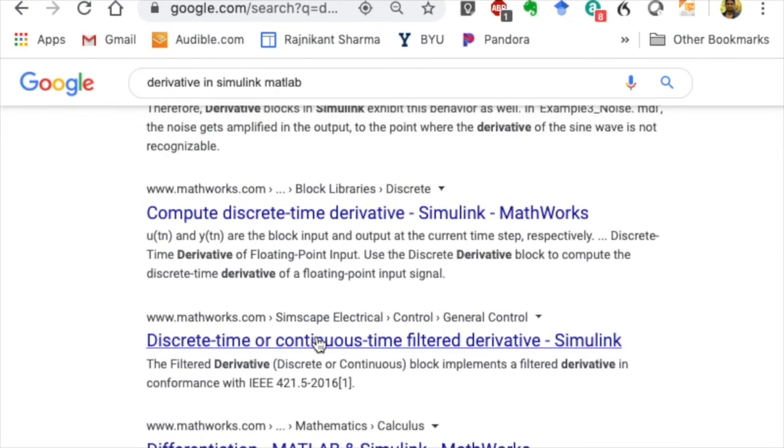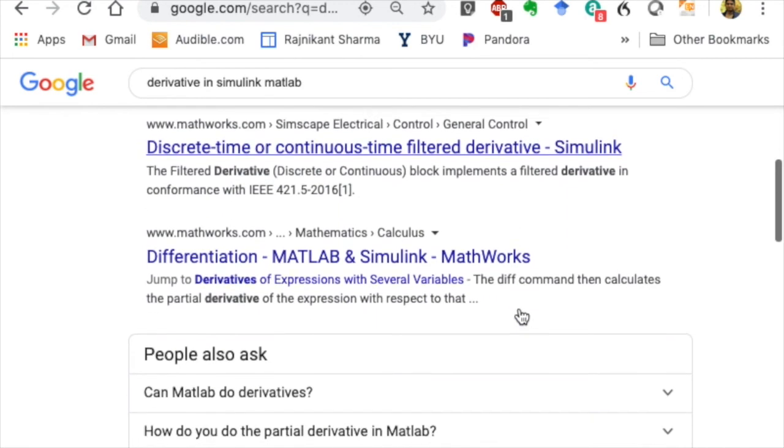So this also raises one good point here. When you are actually implementing things on an autopilot, and when you have a single board computer that you are using on board your UAV or unmanned vehicle, you will not have Matlab there. So you will have to come up with functions that can do the derivative job and the integral job. Here we are pulling things out. So that also we will learn when we are doing the autopilot, how do you actually implement a PID on a single computer without Matlab. So that we will be learning that.